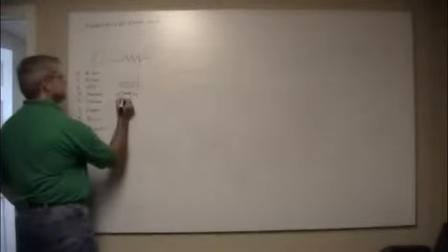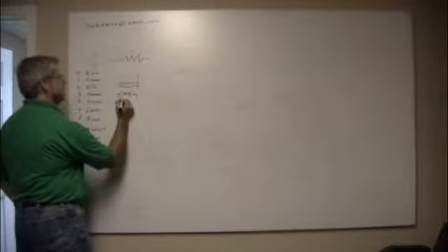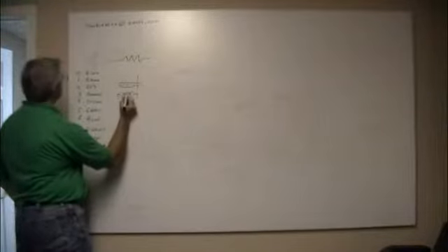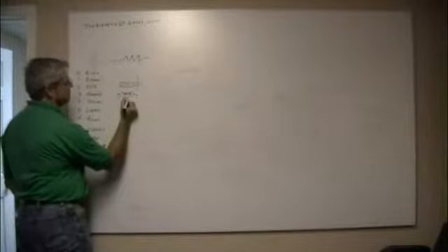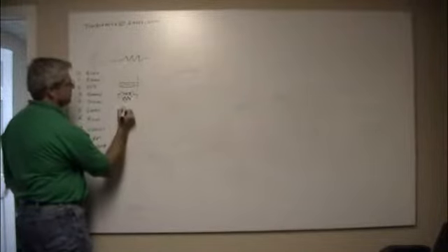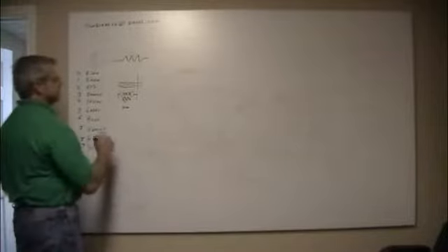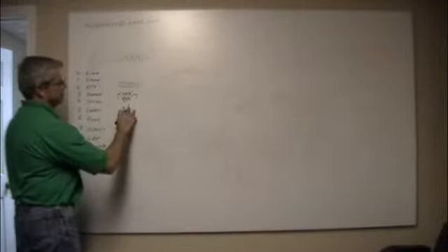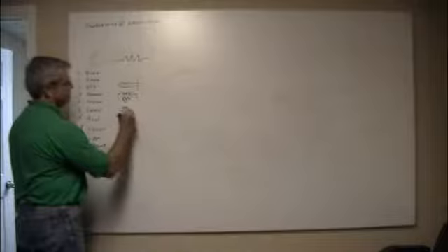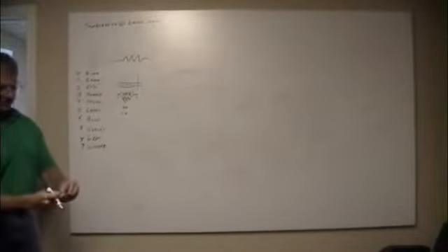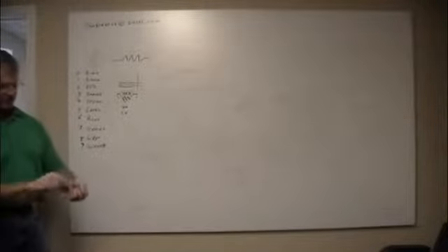And so let's say this was a brown, black, red. That would be 1, 0, and 2 zeros. So it'd be like a kilo ohm. Simple. Or maybe I might have that wrong. It might be 100. It might be 1.0. Anyway, I don't use them anymore. Nowadays, you get them in a little pouch when you buy them from DigiKey. It's labeled.